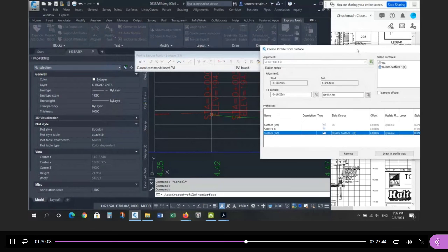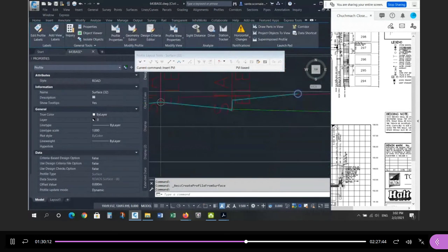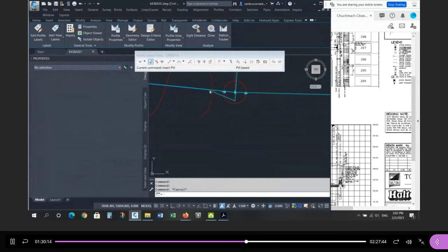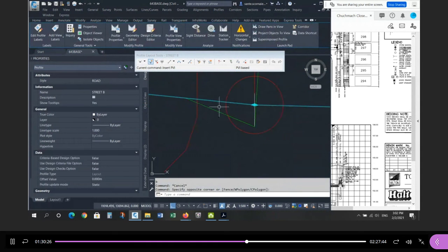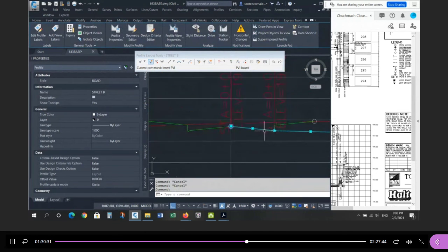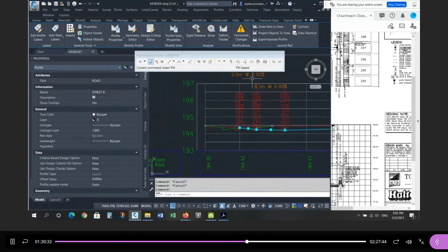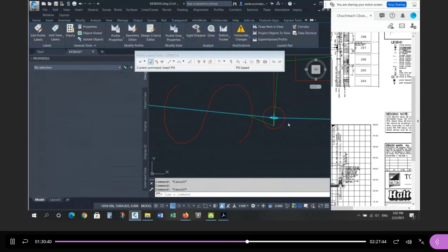It should appear right here. And there it is. The design starts not at the edge of asphalt, but at the gutter location. So they extended the 2% to the position of the gutter. It doesn't start at the edge of asphalt, it starts at the gutter line, which is fine. But this is a 2% plane. So instead of picking up the edge of asphalt elevation, they extended the asphalt to here and then continued.